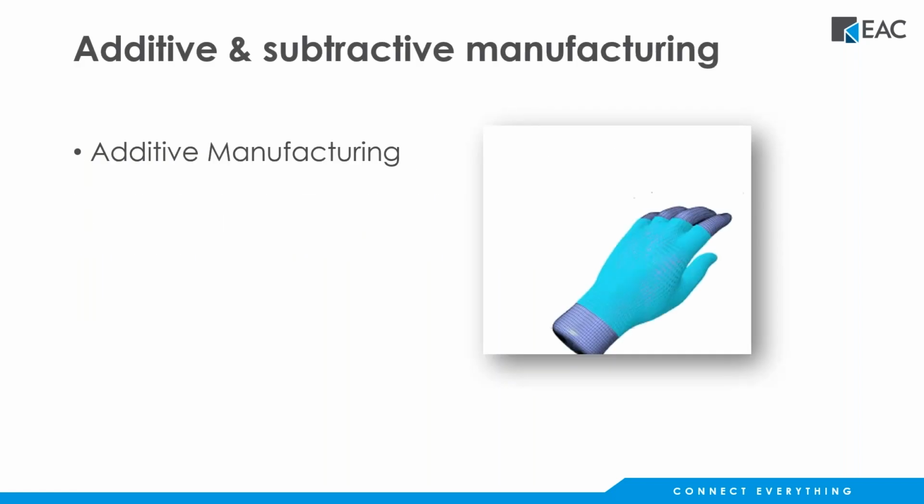So for additive manufacturing, we now in Creo 9 have support for open quilts on stochastic lattices, enabling you for the creation of skin lattices. We also have automatic redirect of fluid flow inside of formula-based lattices. We have a new variable wall for offset formula based on lattices. And we can now mix user-defined and materialized support for structures.